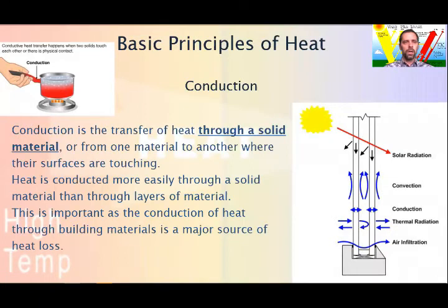So first we talk about conduction. It is the transfer of heat through a solid material or from one material to another where their surfaces are touching. Heat is conducted more easily through a solid material than through layers of material, even when the layers are held together tightly. This is important as the conduction of heat through building materials like walls is a major source of heat loss. In other terms, if you put a pot of water to boil on the hob and a little later you touch it, you will understand conduction.